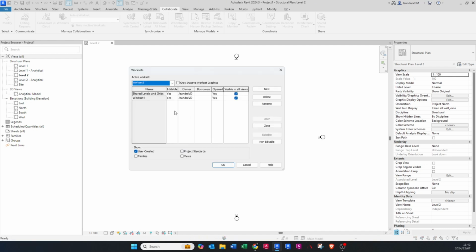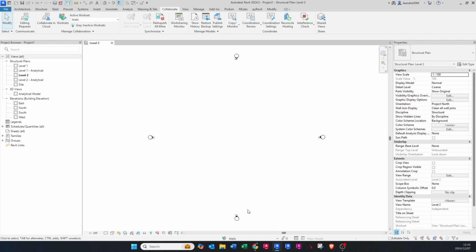You'll see if I click on this, you just say okay. Then it's going to give us a pop-up here. Then these are two work sets that are automatically created by Revit. Then you can create your own one here. Let's, for instance, just call this walls. Say okay. And then say okay again. And just, yes, I want it to be the active work set. So you'll see here at the bottom, you have 3 work sets. I refer to it as the same type of layers that you get in AutoCAD.